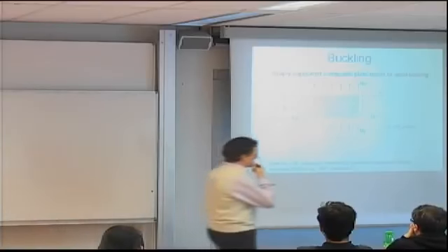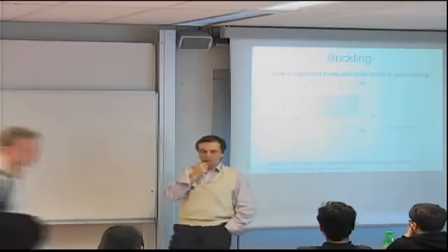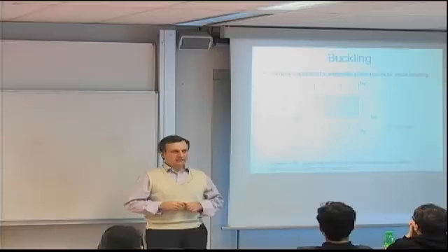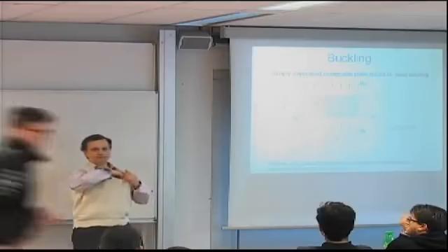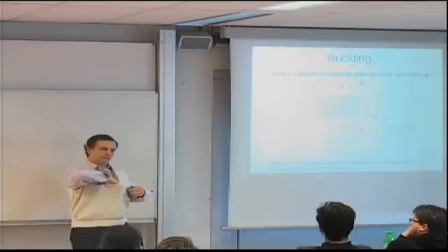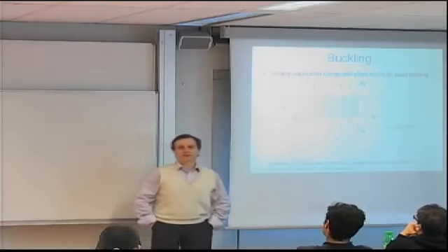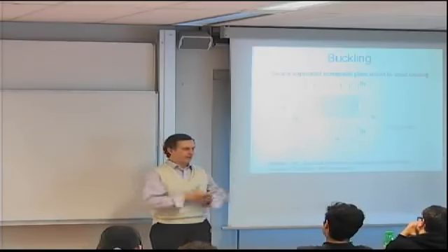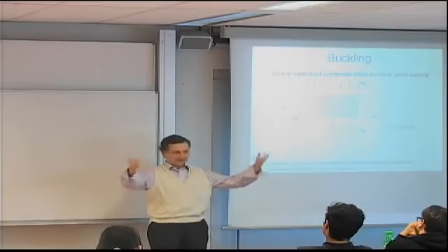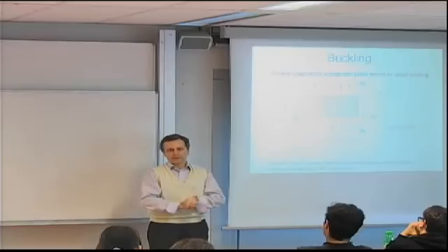Now there's an interesting question related to the B matrix. Suppose that the B matrix were not 0. What would happen then? And what's the meaning of buckling in that case? Buckling is a phenomenon in which you increase the load from 0 and the structure deforms in its plane, or it maintains its original shape, let's say if it's a cylinder, until all of a sudden all heck breaks loose and it starts deforming in a completely different direction out of plane for a flat plate, for example.